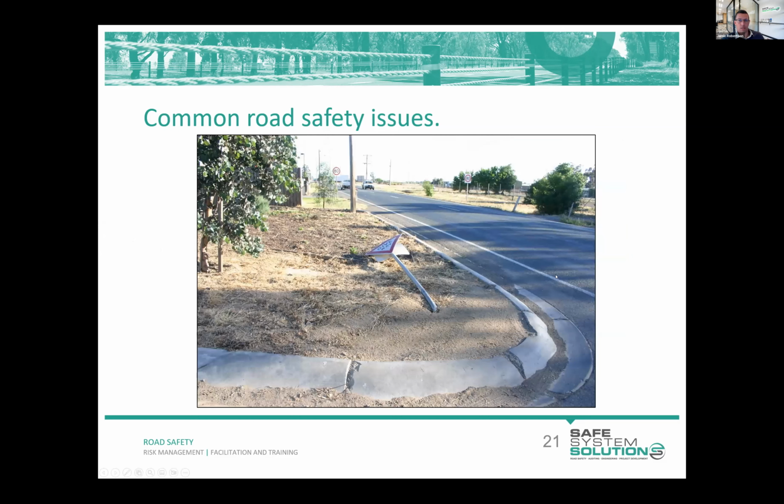It's common to see signs knocked down on our roadsides, and this can point to a lack of space. Another common example is the keep left sign on a splitter island. We often see them knocked flat. It's a common situation to use a sort of rebounding post. In those situations, it can point to a lack of space for a turning vehicle.